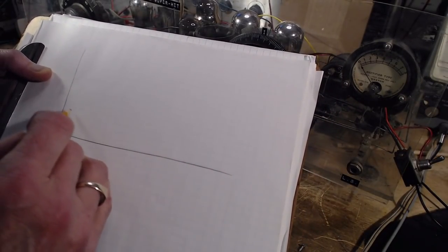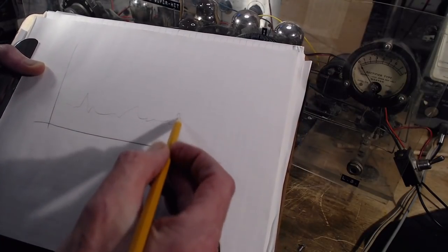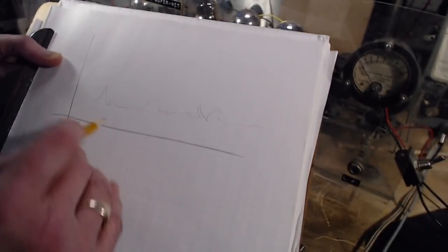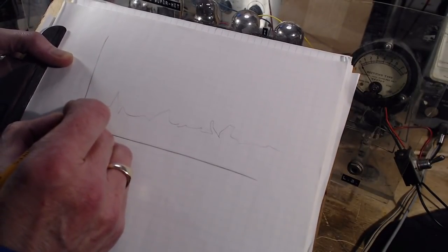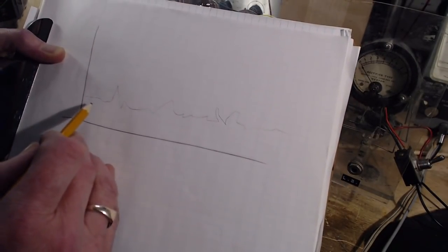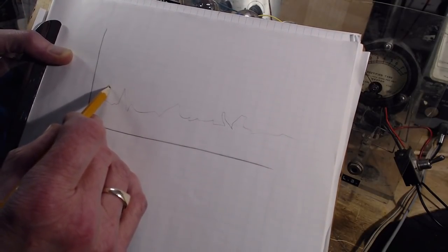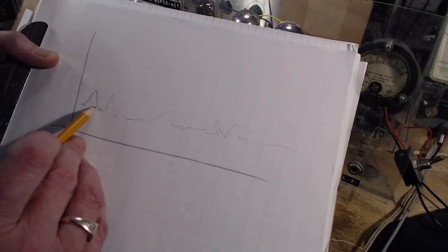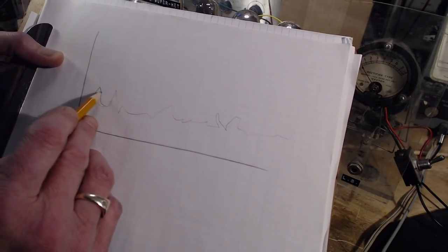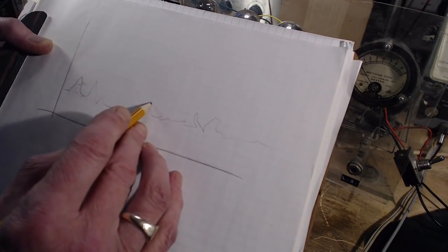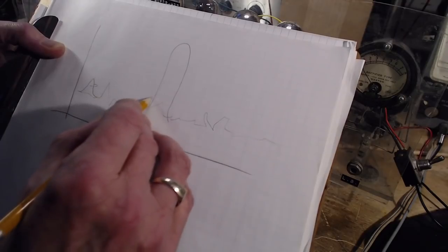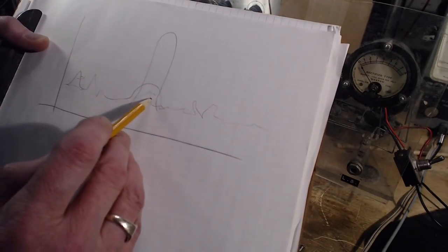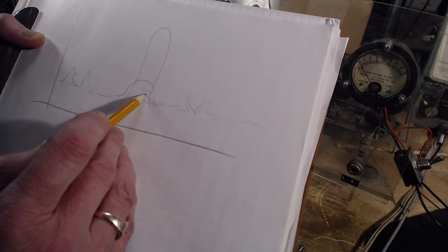So when we look across on my SDR, you see various noisy signals here like this. And then somehow, as I tuned this radio, something was happening where you could see a peak. Now this is hard for me to draw on a piece of paper, but it would start about here. And what's happening is everything in this area is boosted. So as I move this peak forward, as I tune this knob here, let's say this got all the way to here, this thing, which I drew terribly, would then leap up as the tuning point went by. That's an indication of a resonance, not an oscillator signal, a resonance.